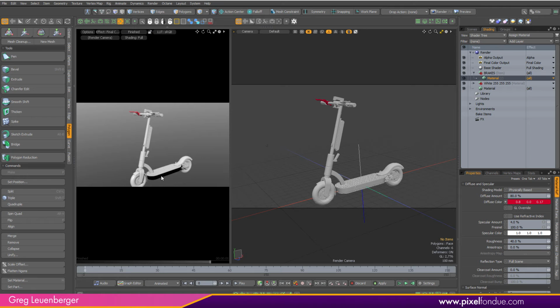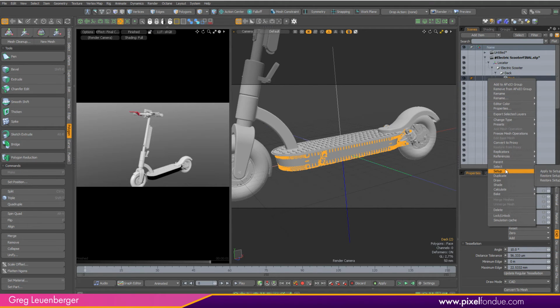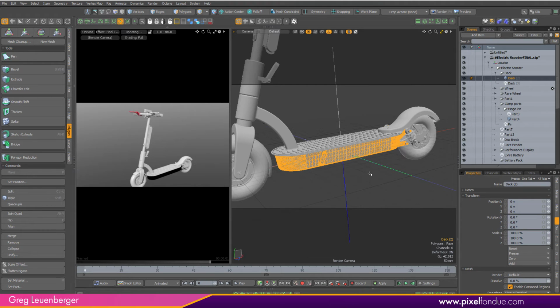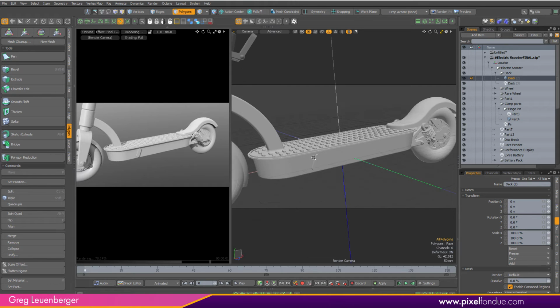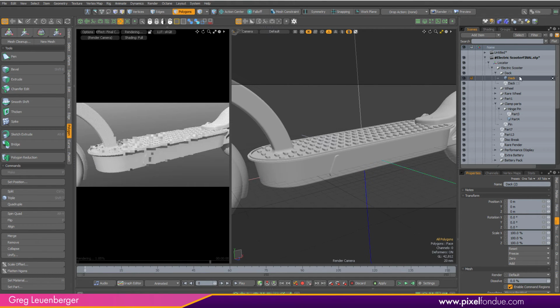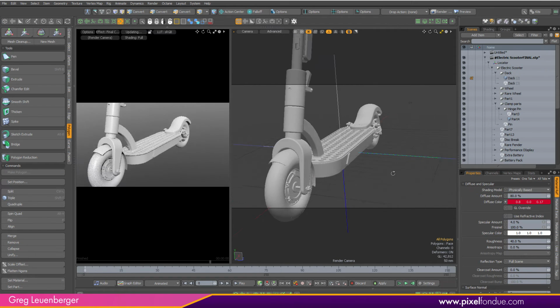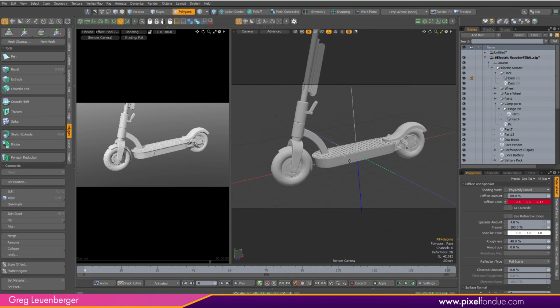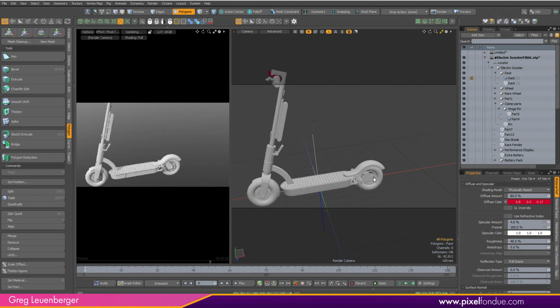You'll see I'm getting some weird normals down here. So I may want to, let me just select this guy. And this is the one that was flipped, if you remember, when we loaded up as just meshes. So let's change this to a mesh and flip it by pressing F, and yeah, there we go, it fixes it. So you can do some cleanup in the CAD item method as well. You just convert them to meshes and do whatever cleanup you want. If you want to add surface decals and things like that and do some UVing, no problem.